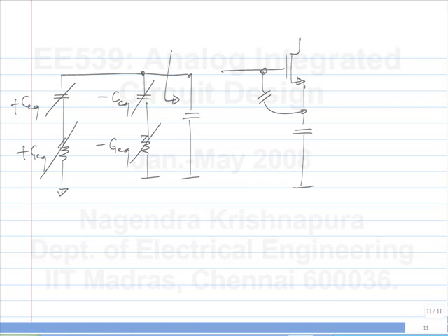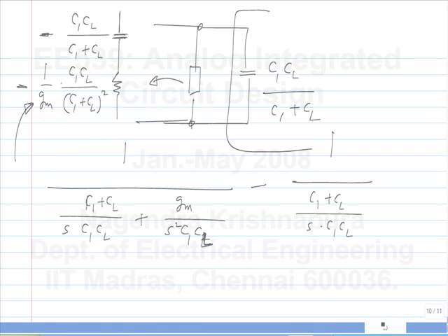You are left with only the capacitance. So if you are having problem with stability of some amplifier stages because one of the amplifiers is presenting a negative impedance, you can connect a positive impedance. And this representation helps you to calculate exactly what it is that you need to put. And in fact, you can put this because this is a fixed resistance, right? You know what the GM is, your bias rate.